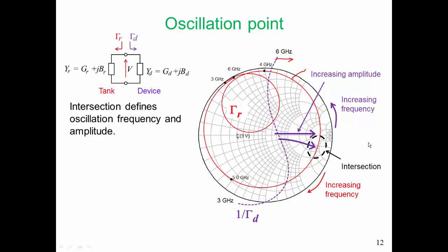So part of our design strategy as we get more involved in design and get closer to the final design is we want to follow a line of constant susceptance so that we have an intersection point around about here. Now we could follow other lines of constant susceptance as well. In this particular design, this is the line that we follow. And so our point of intersection is in this region here.